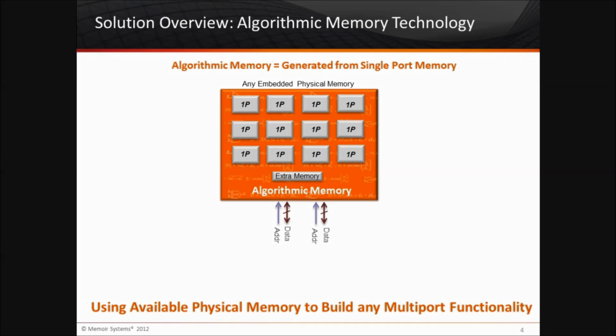The next thing is that both these ports can access the entire memory address. There are no restrictions whatsoever on the addressing capability. Third, we allow simultaneous accesses to any row, address bank, or column. There are no exceptions whatsoever to the address pattern. So what's shown here in this diagram, if you view it as a black box, is a true dual port memory. If you build an algorithmic dual port memory and replace it with something that used a circuit-based or transistor-based approach, with 8 transistors per bit cell, you could not distinguish the 2 memories. And that's the hard claim that we make with the technology.